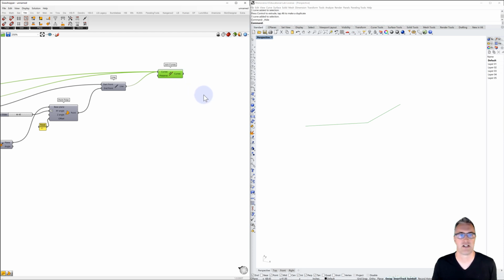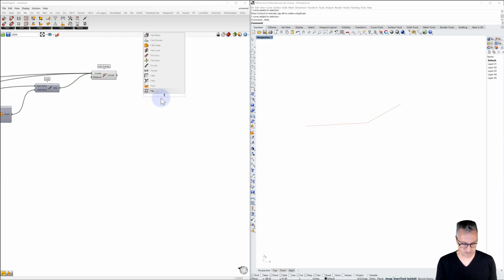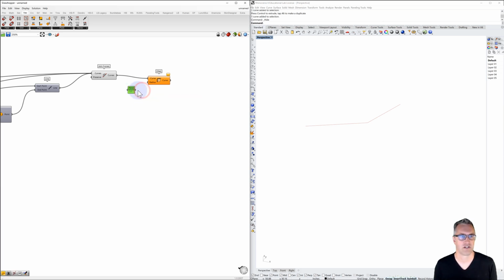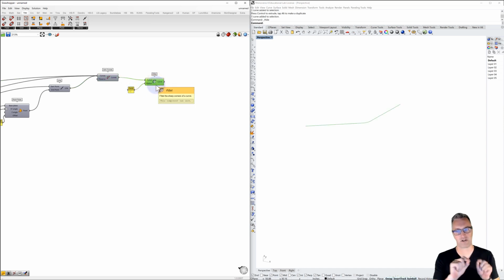So from that, let's fillet this. That's how I was creating the radius. So we'll fillet this curve, and our radius, let's set to be 12 inches. And when I'm being specific about a dimension, I'm not using a slider. And so that way that will be consistent. Now we see we have our first line, the extension of that line for 48 inches, a radius, and then the 48 inches from there.